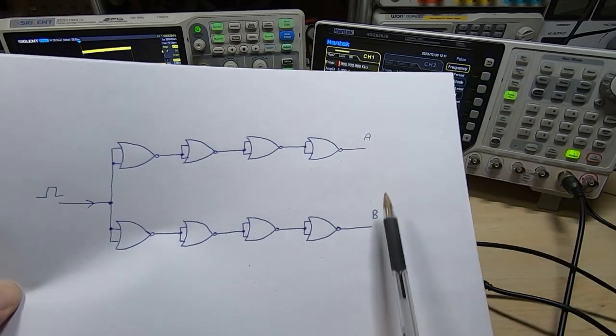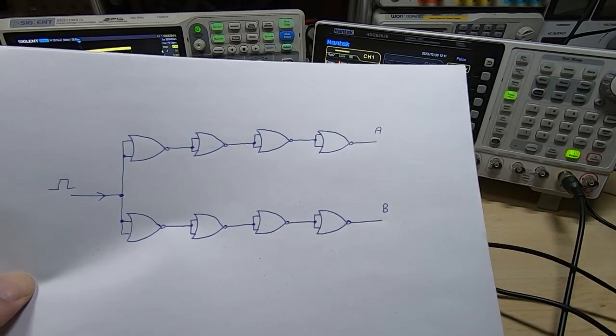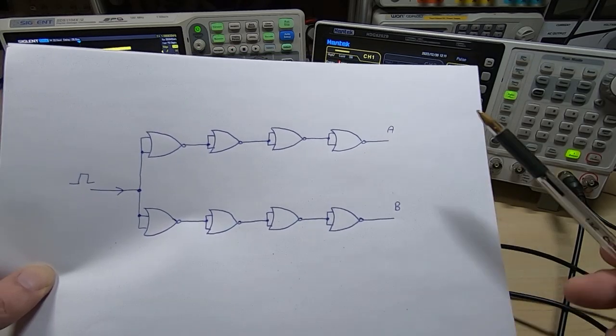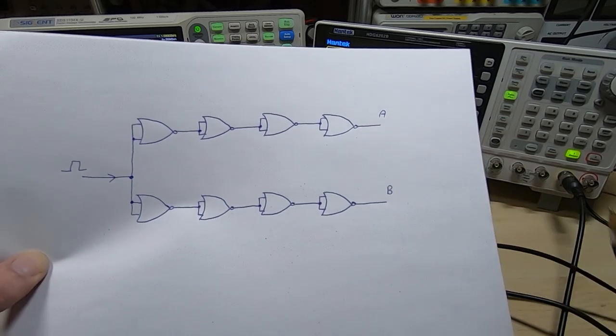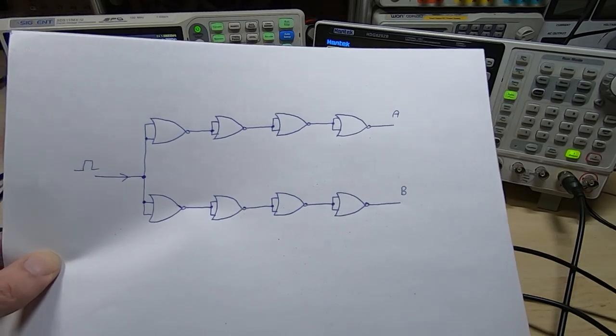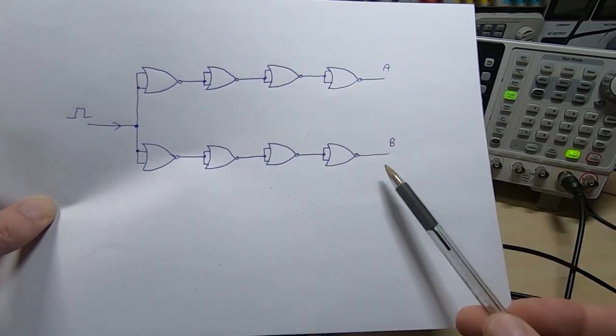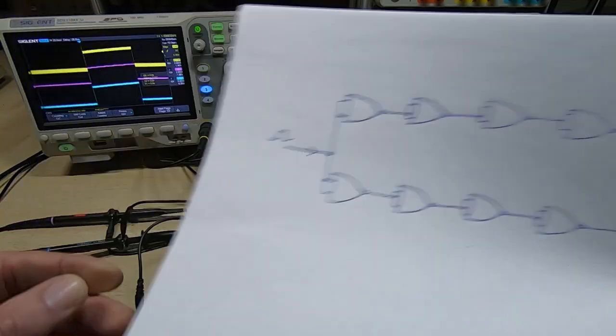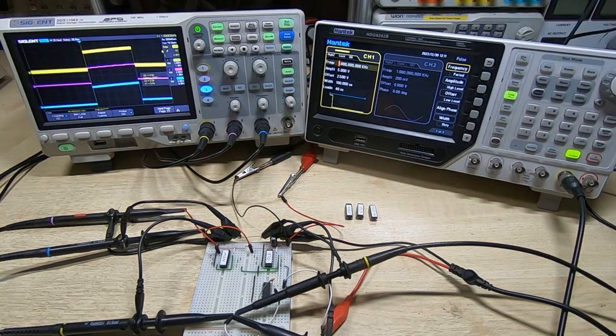We're not saying that these two signals are driving the RAM or whatever it is directly, but it can show a difference for, if for example one path is for the chip enable for an SRAM and the second one is for a write enable for the SRAM, and that can have a major impact if they're not correctly timed.